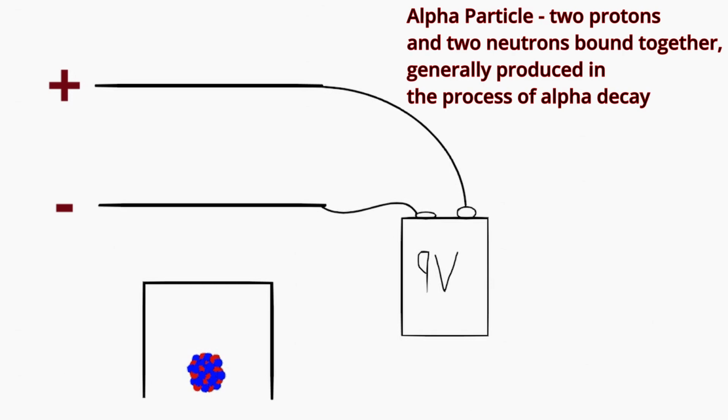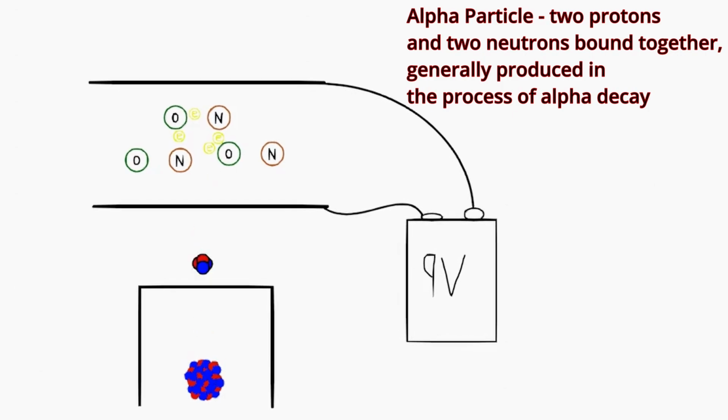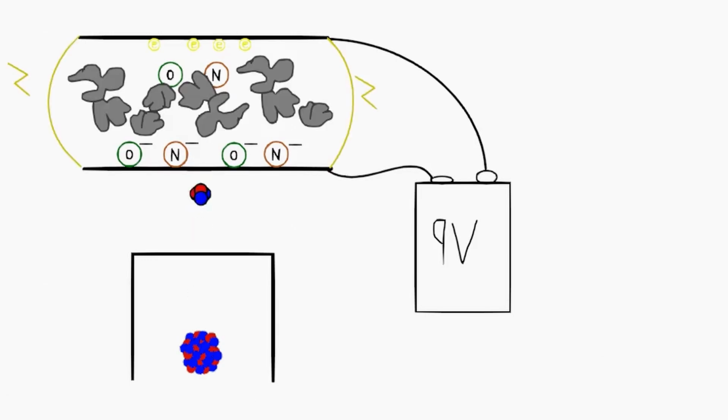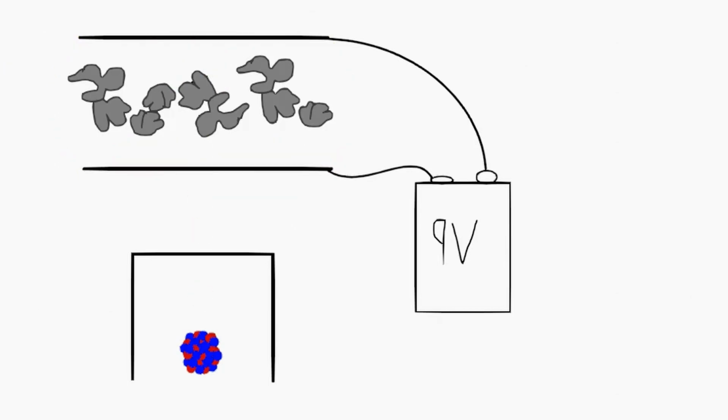negative. Alpha particles, constantly released from americium-241, knock electrons off of the atoms in the air, ionizing the oxygen and nitrogen atoms in the chamber, and cause positively charged oxygen and nitrogen atoms to bind to the negative plate and knocked off electrons to bind to the positive plate. This generates a small, continuous electrical current, and when smoke enters the ionization chamber, the smoke particles attach to the ions and prevent them from generating this electrical current, which triggers the smoke alarm.